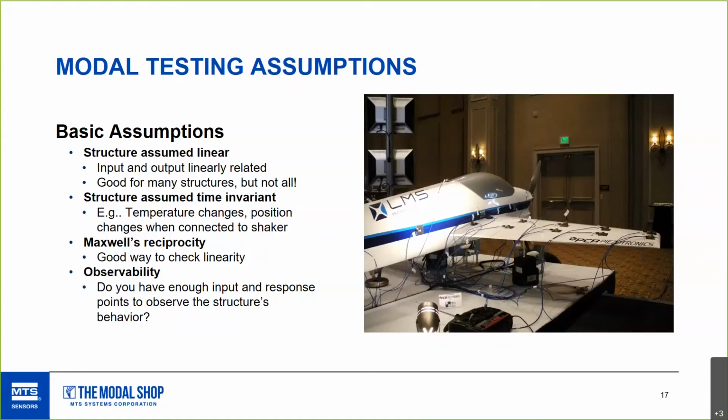So one good tip there, to interrupt quick: a lot of people, if you're going to start roving sensors or something, before you change, try to eliminate things like time invariance. If you're doing the next setup the next day, keep your structure set up the same way as the prior day. Fire everything up the next day and do another quick sanity check on your test. Duplicate what you'd done before.